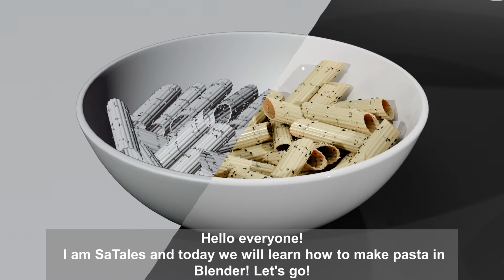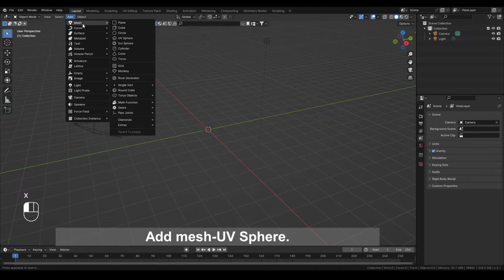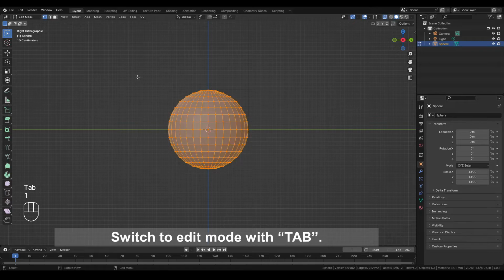Let's go! First, select the cube and delete it with X. Add mesh, UV sphere. Change view to right orthographic view with numpad 3. Switch to edit mode with tab.